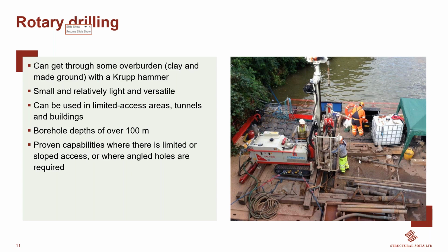But we've got an SPT hammer here. This allows us to undertake standard penetration testing, and this will give us an indication of the strength of the ground as we progress through the borehole. So we can get up to 100 meters, not necessarily with this 205. We'll probably get to 40 or 50 meters with the 205, but if we're looking at the Komatsu 600 series, we can get a lot deeper with that. So again, depending on the site constraints and the depth of the client's requirements, we will choose the size of the rig that suits the job that we need.